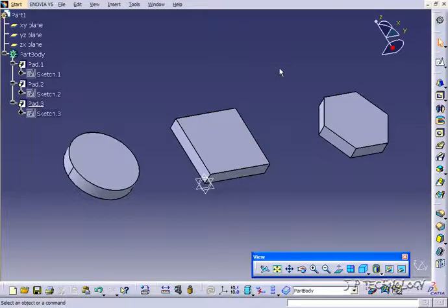So what we're going to be doing is creating a sketch on these solid bodies that we've made, and we're going to do the drafted fillet pad off of it. Now, the drafted fillet pad saves you time as it introduces 3 features into one step. In this one step, you're going to be extruding the part, drafting it, along with adding fillets all over it. So this tool is a real time saver as it combines 3 steps into one quick and easy step.